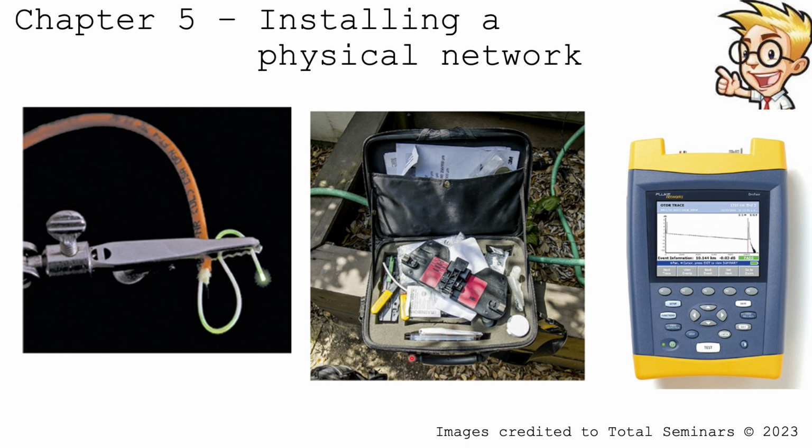A lot of technicians need to cut fiber or splice it in the field. So you'll have a field bag with all kinds of tools to cut and splice and get the cable back up again. And here's an optical time domain reflectometer, which is used for optical networks, but does the same thing.